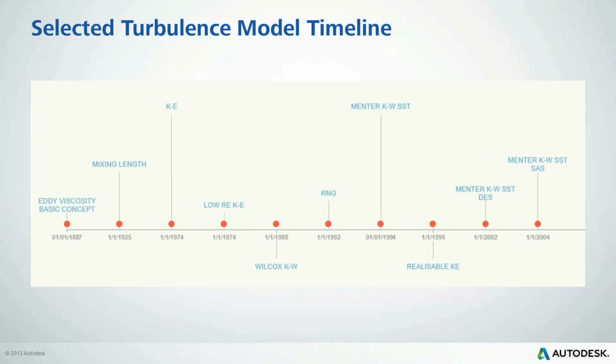I don't really want to get into that conversation too much, but I wanted to emphasize that this is a very growing modeling technique. Outside of that, mixing length is a very simple modeling technique where you're just changing your viscosity, for instance, just along the wall. Everywhere else is just a constant value of viscosity.